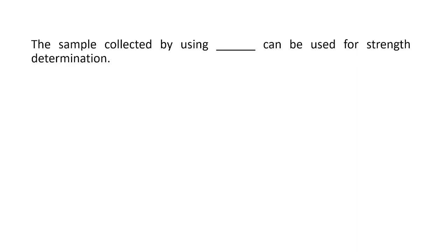Whether we go for shallow or deep geotechnical investigation, we have to collect samples. In shallow geotechnical investigations, we generally limit it to a few meters depth below the seabed, not below the seawater, because after the seawater the seabed starts, and then we need to know the stratification of the layers.